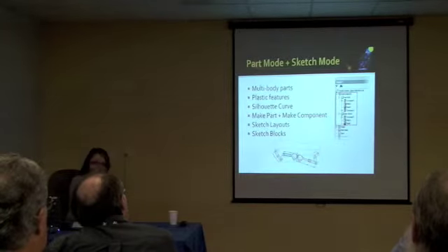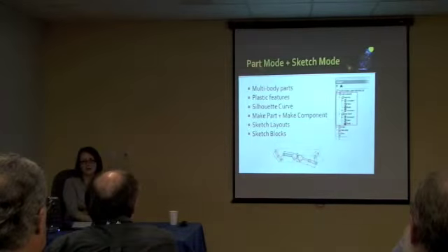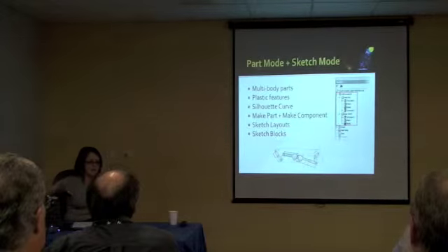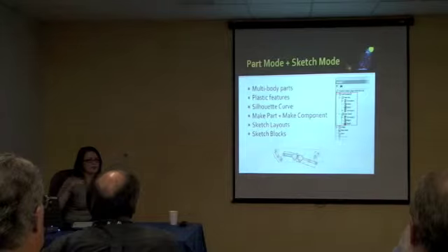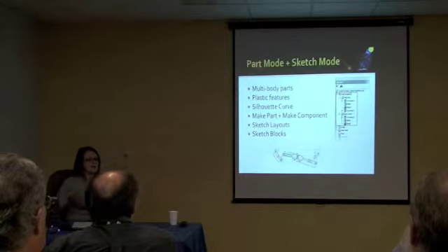We've got some plastic part tools that Rod talked about briefly, which enable you to create grills, lips, clip fasteners, a whole array of plastic features a lot more easily. There's a silhouette curve option that allows you to take any skeleton model you've made and take a sort of 3D sketch projection of the outermost extents of it and just present it as a 3D sketch to you.